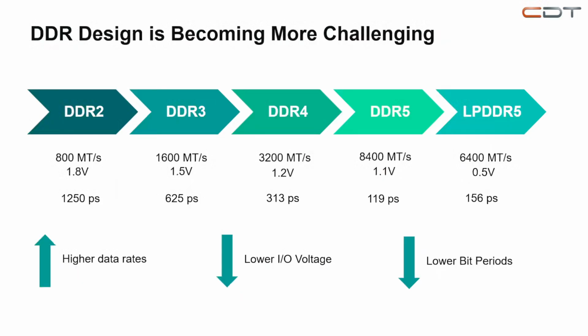Today we are specifically talking about DDR because, as all of you know, it's something we get a lot of questions about. It's an extremely common interface, but it's also one that is kind of complex. It's constantly evolving, and you can see it on this diagram. The numbers are not too important, but the point is that the periods are getting tighter and tighter, and our constraints have to evolve with the changing interface. This can be a little bit daunting, but we will talk about how we can set up formulas for different examples. And hopefully everybody leaves here feeling a little more comfortable diving into formulas in Constraint Manager.